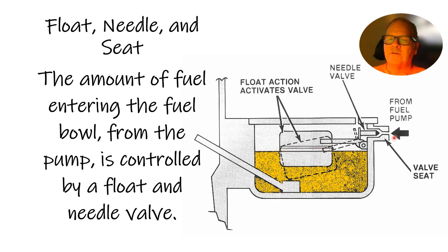Now, if you had a clogged-up fuel filter and it couldn't get the fuel in there fast enough, and you were really getting on it, this would drink that fuel out of there fast enough that you'd start losing power. That's when you notice it. A fuel filter: some people would say, well, my vehicle wouldn't start, maybe I'll change the fuel filter.